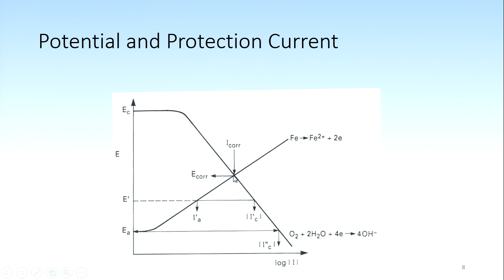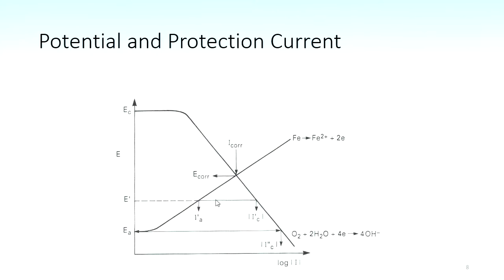What you have got on your handout is this diagram, which is to remind you that, of course, with the oxygen reduction reaction, we've got about 8 parts per million oxygen in the solution, in the groundwater or in the seawater, probably less in the soil actually. And so there's a mass transport diffusion limit for the oxygen. By Fick's law of diffusion, the oxygen will migrate down the concentration gradient to the electrode.